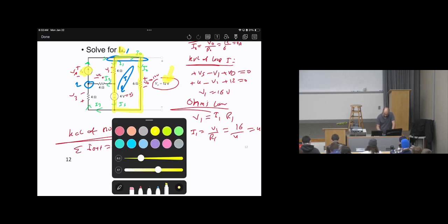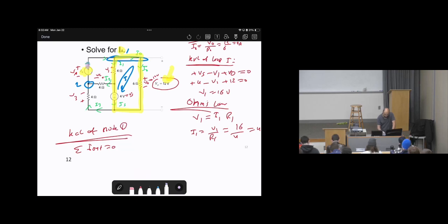Now, let's look at these currents. We have IA going this way, which is entering, so it will be negative IA. Now, I1 is leaving, going down, leaving this node. Therefore, it will be positive because it's leaving. IO is leaving. It goes here and leaving.